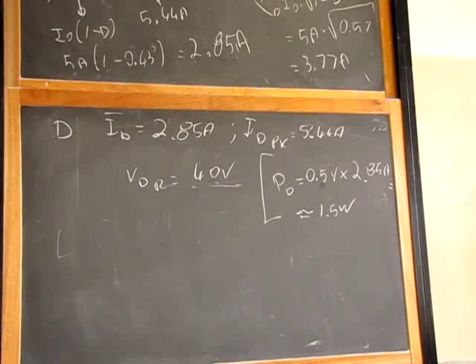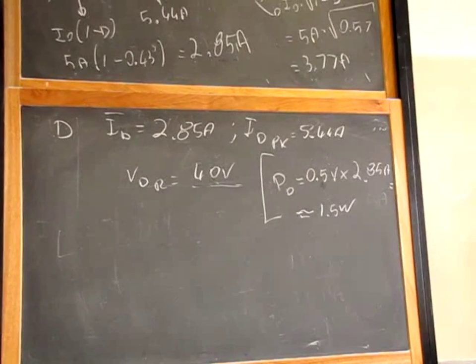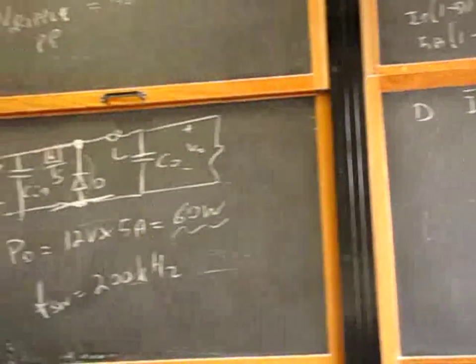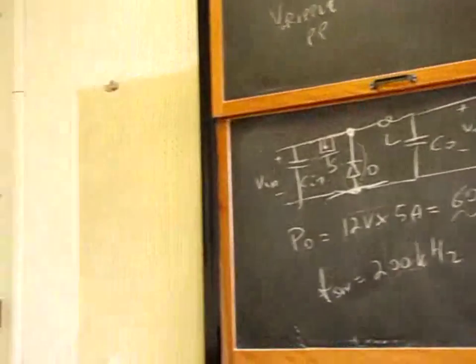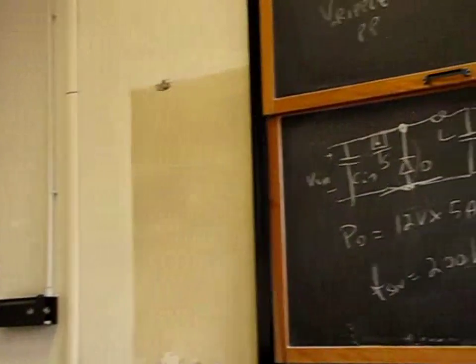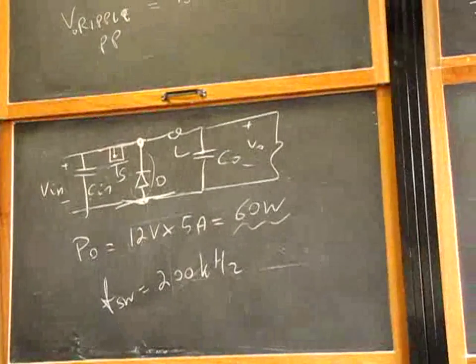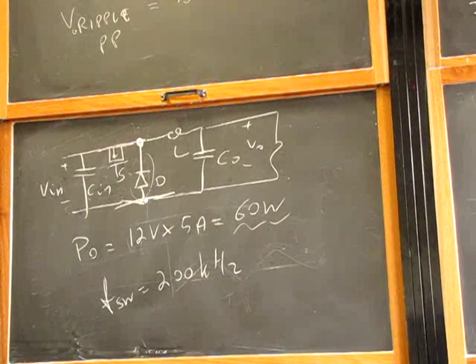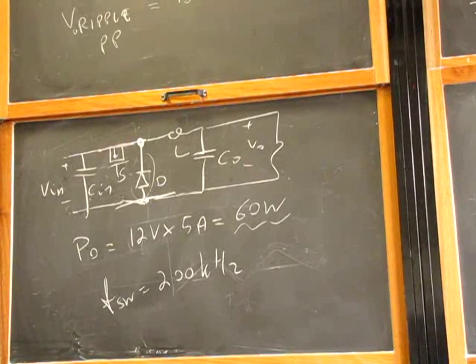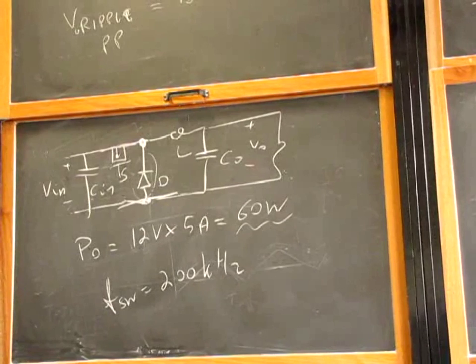If you use a PN diode, you cannot take the first diode you find on your workbench. You cannot use any diode like, for example, the 1N4007. You know, the 1N4007 diode is everywhere. Well, this is too slow. You need a very fast recovery diode for switch mode, not any diode. If you put a 1N4007 or whatever in a switch mode converter, your converter will just gulp it, literally.